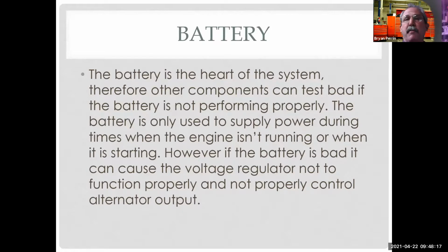On the other hand, my battery could be bad and saying, I'm really, really hungry. You've been eating all day and you haven't done anything. Yeah, but I'm really hungry. And the charging system is going to keep pumping stuff in and cause it to overheat or boil over or other issues. So the battery is the first thing we test. If I suspect any kind of starting or charging problem, or any kind of computer problem, I want to make sure the battery tests good, especially if it's a weird computer problem or intermittent problem, just to eliminate it.